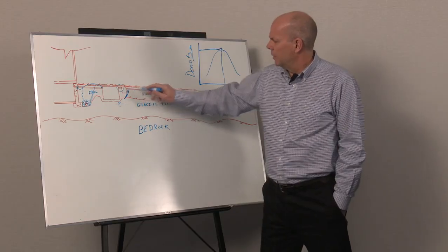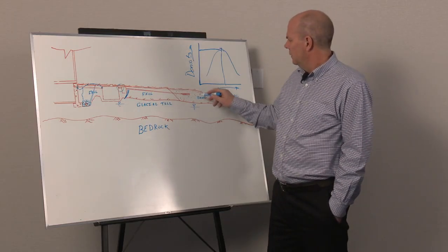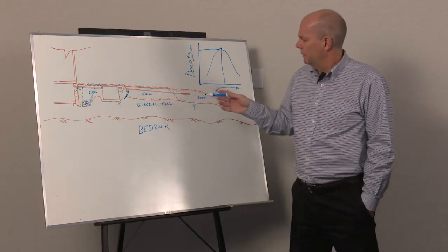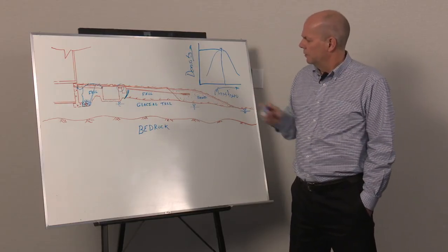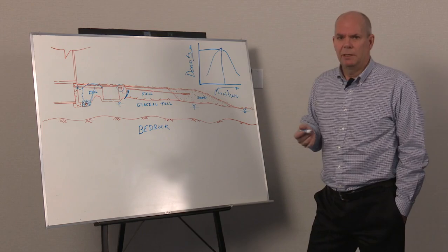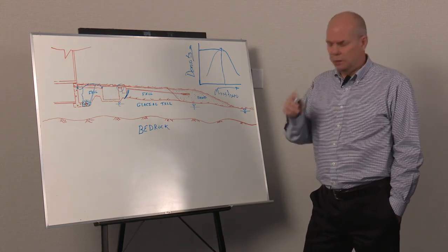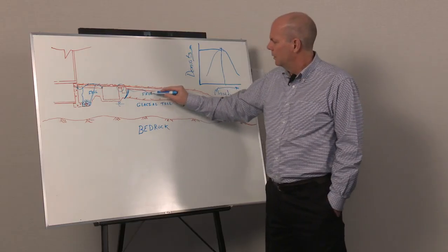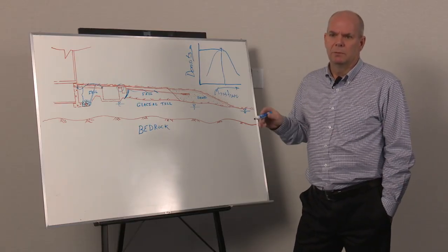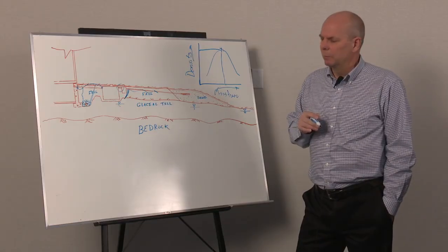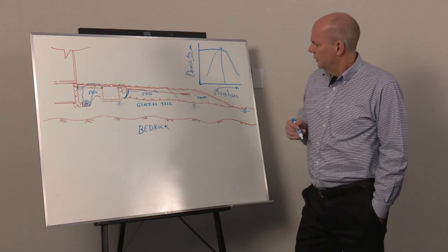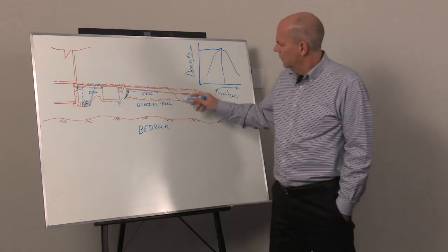As you leave the pump chamber, siphon box, going out into the sand bed, same conditions. You may be partially in fill, you may be partially in fill and glacial till. It all comes back to the behavior of the fill. If it's been placed previously and it's not good quality, you can have differential settlement along that pipe. And any differential where you're dealing with a low grade on the pipe, it doesn't take much to start to pond water, collect water in the pipe, which causes solids to collect, and that starts problems with plugging of the pipe. So make sure that this fill is looked after.